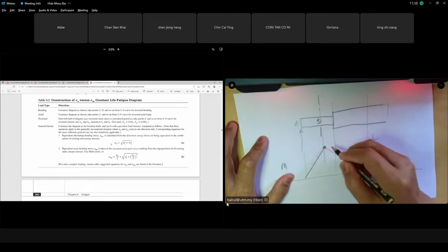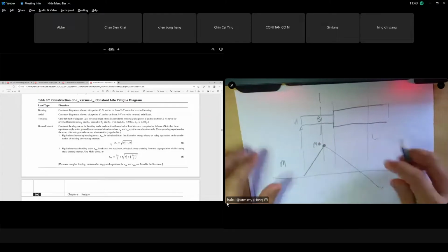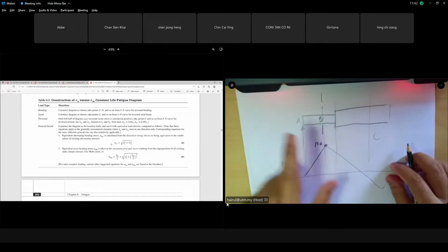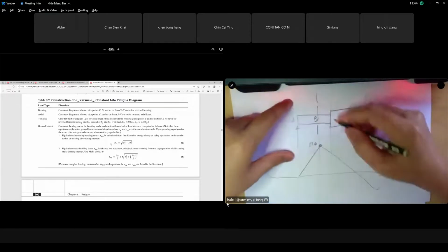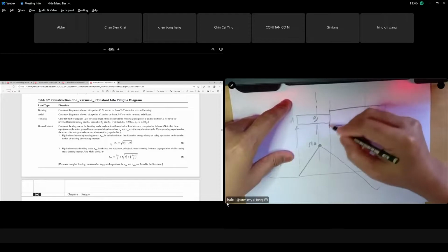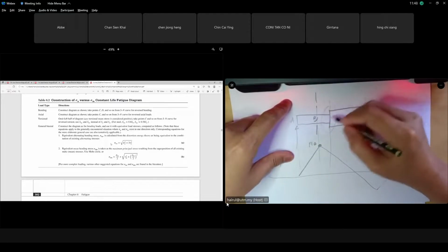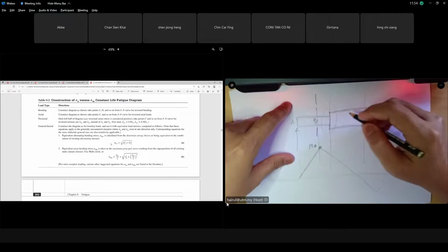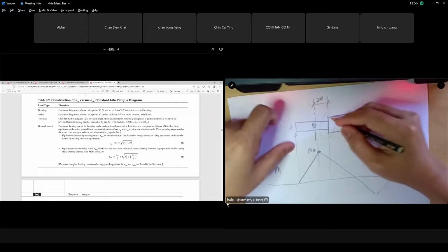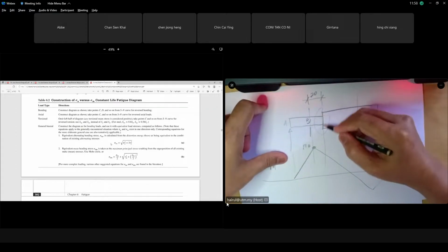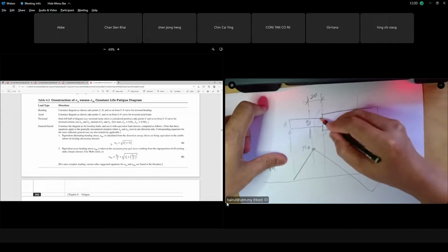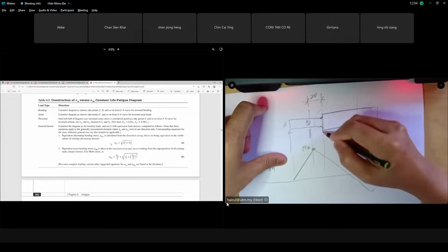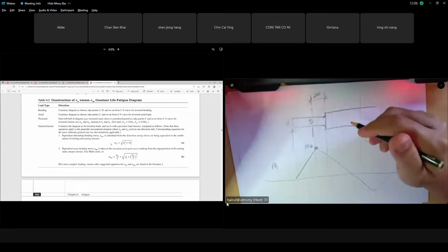So you find that this is the critical moment at B, and this will create bending stress. But our point of interest, we need to consider at the shoulder, maybe at a distance of 20 millimeters to the right. At this shoulder, if you zoom in, there is a fillet radius, so stress concentration will happen there.